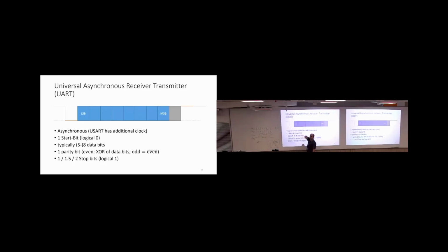How should you sample this signal in order to find out at which point in time the first thing here comes? Flip-flop you would need to store, but how to sample it? With which frequency? Yeah, but which frequency should the clock have? So if you want to have a concrete number, let's say this here is 1 microsecond. You can also say period length, and it's easier, and you do not have to divide.